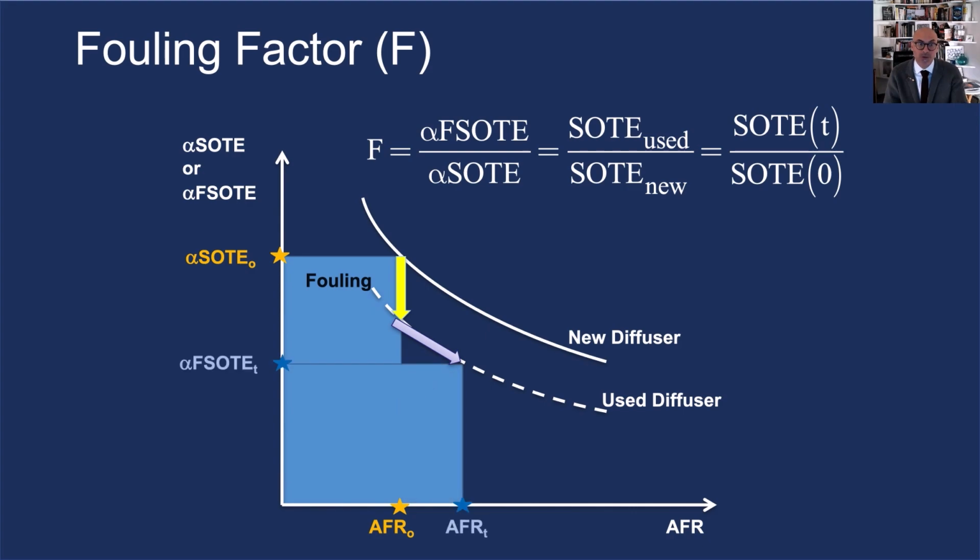This is what the controller does, releases more air to compensate and to get the same dissolved oxygen in the water. Now I need more air because I have less efficiency. You see, the areas of the two rectangles are the same. And what happened is I don't just go down to the yellow extent, but to the red one, because now I'm in a less desirable operating point with more airflow, okay, over time. So I have a lot less efficiency in proportion.